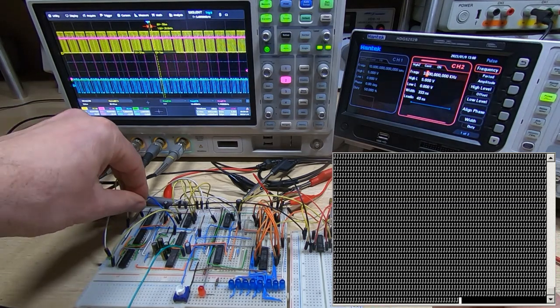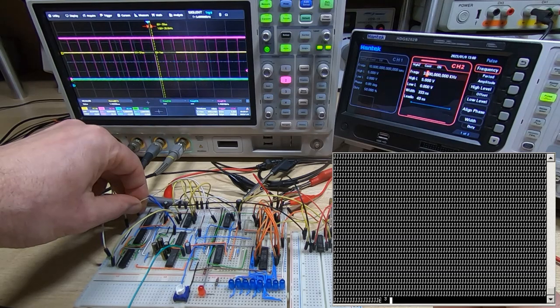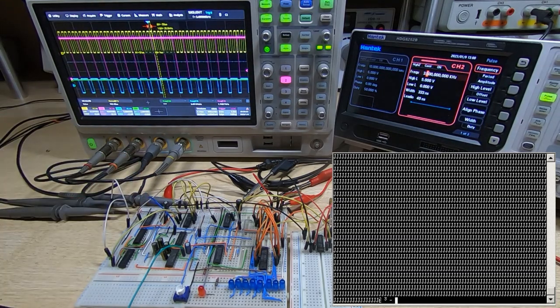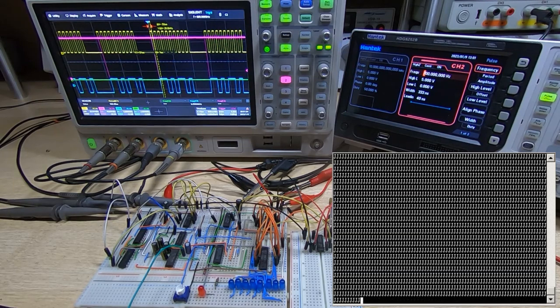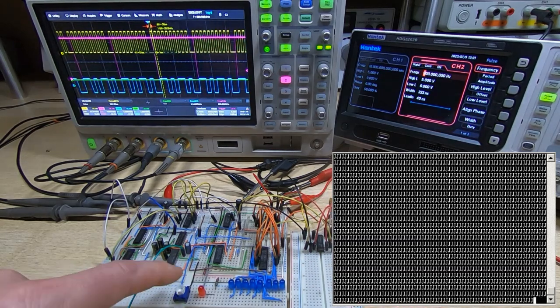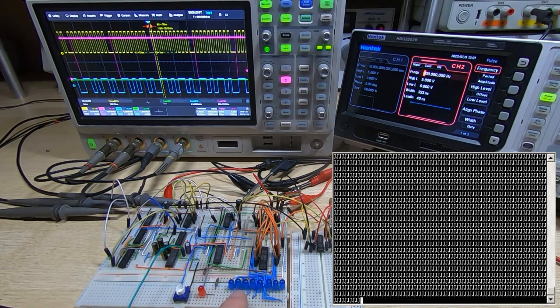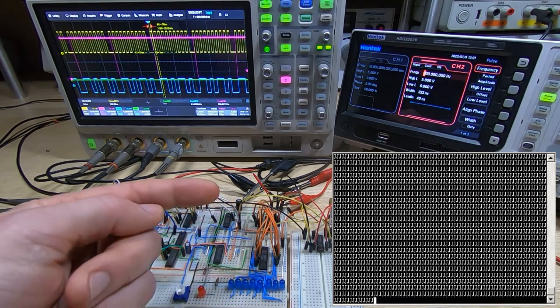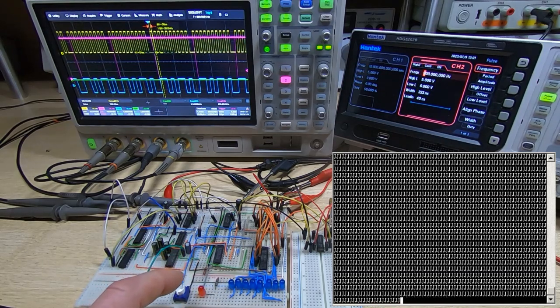I'm just going to go back to 9600 baud. I'll change the terminal as well. So as you can see, once again it's working the way it should, back up at 900 characters per second. But of course we have the second part of the circuit, so it is a full duplex system we have here. Now this button that we have is to allow us to read the value that's on the receiver buffer, and also to reset the circuit so it's ready to accept the next data value.